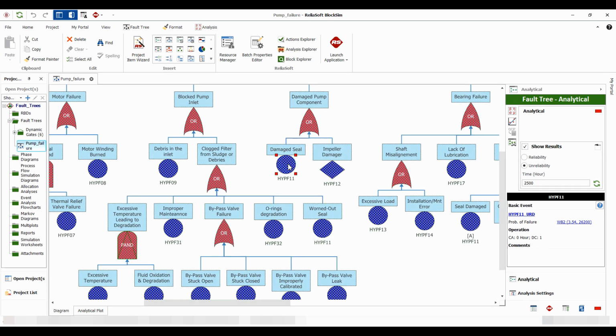So we have the same failure distribution, and we haven't actually indicated that this, for example, refers to a specific seal and these others refer to another specific seal. So we can only come to the conclusion that this is a generic damage seal function, failure distribution, and therefore we're wondering whether putting in two independent events, like in this case, actually makes sense. So what we can do is use one of these elements and then mirror it down here onto the other element.